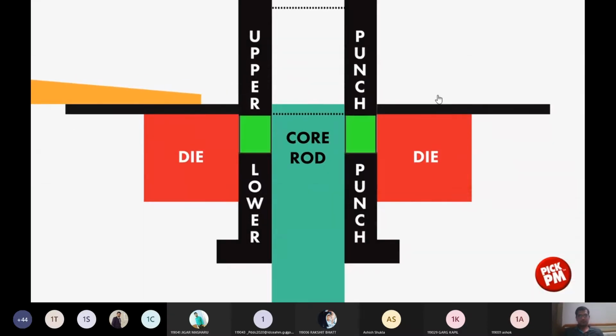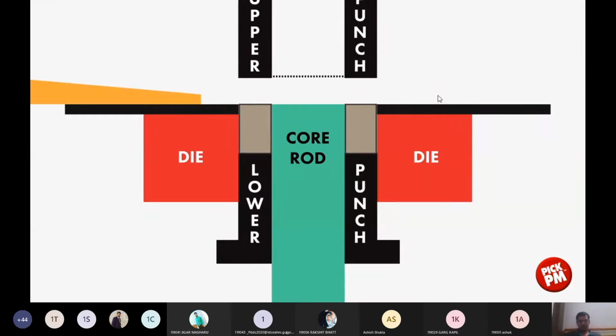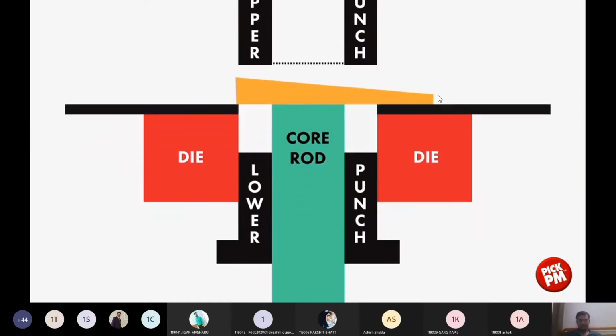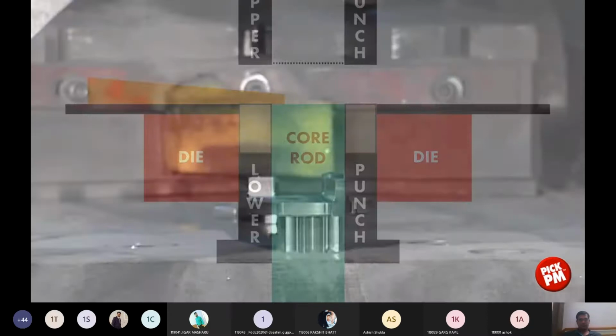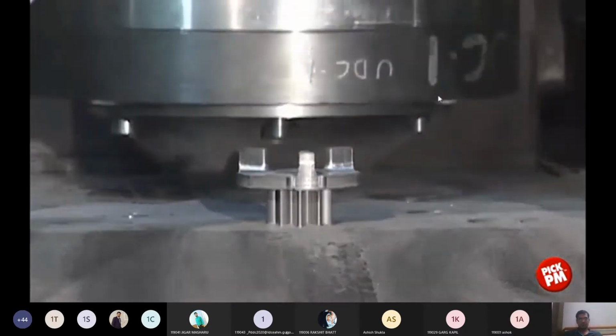The upper punch closes off the die after filling the cavity. The lower punch remains stationary. The die travels down. This process is known as withdrawal type compaction, and you can see the green component that's formed. Compaction establishes the density of the powder metal compact.